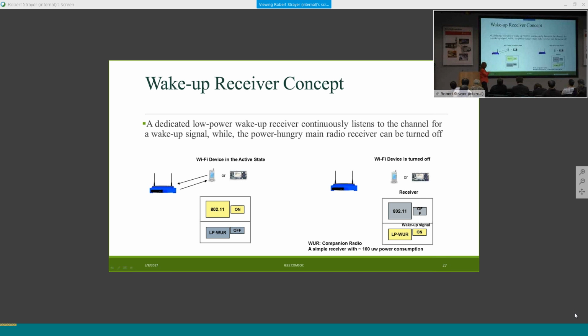It can be a very simple radio, which with new advances in RFIC development can really consume around 100 microwatt active power. So 100 microwatt seems very aggressively low, but it has been researched in academia, and published papers report that they have achieved this. The way they achieve this is by using an on-chip oscillator, like a ring oscillator or LC oscillator. Those oscillators, as opposed to an external crystal, consume much less power. The really power-hungry components of receivers are the oscillator, the LO and the PLL, and the low-noise amplifier.